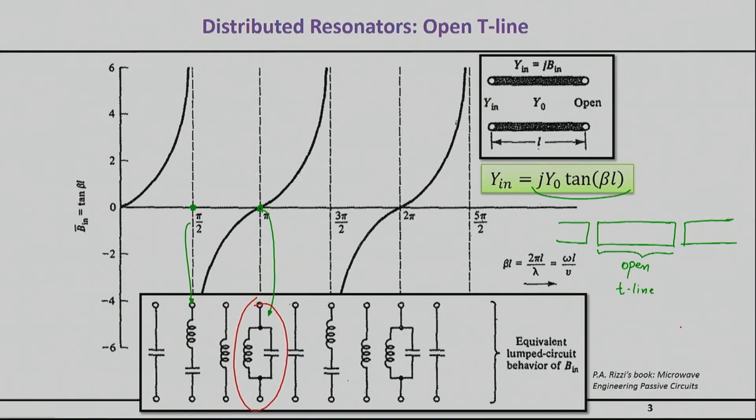My realization will be a coupling section, which will be done with a gap, and I'll explain more about this. Then I want a shunt LC, and then another coupler, and another shunt LC. Now, in the next lecture, I'm going to show you, in case you're wondering, why we're using a transmission line to implement these LCs, and why we're not using, for example, a real shunt L and real C. The preview of the answer is that there are certain frequencies where you cannot use LC.